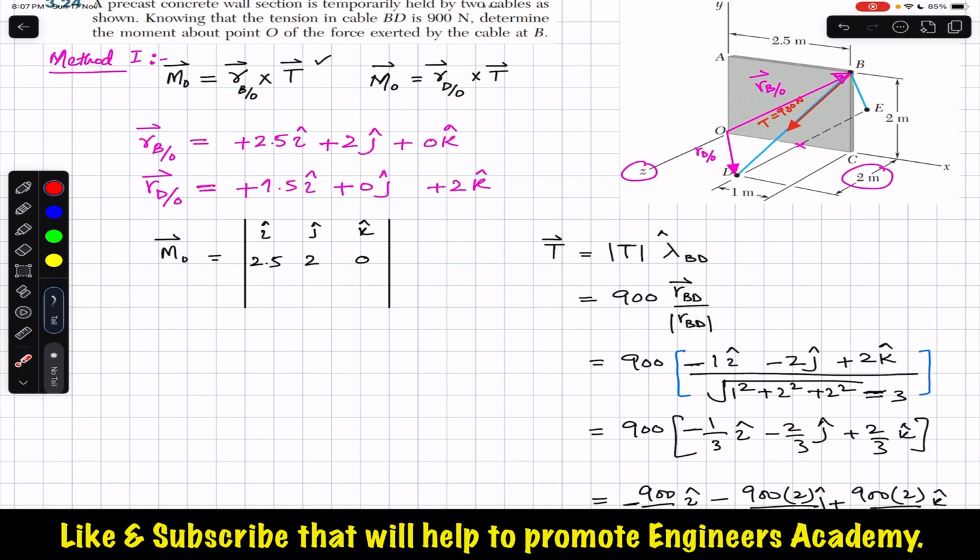So now as we can see, the tension from B to D is acting like this. Its x component is negative, since it is going in the negative x direction. Its y component is negative as well, since this vector is going in the downward direction, that is in the negative y direction, and its z component is positive.